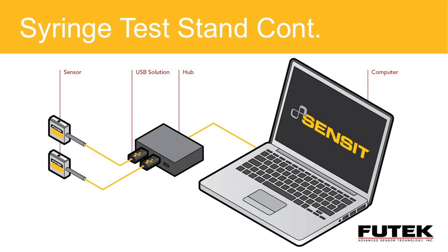An application that is related to the syringe application is fluid injection for imaging work in soft tissue medical imaging, such as MRIs. Fluid material needs to be injected into the soft tissue to get the proper image, and this needs to be done at a specific rate. In those applications, a load cell is used behind the plunger. An actuator is utilized to move the plunger, measuring the force via the load cell. The rate of fluid dispensed is monitored.